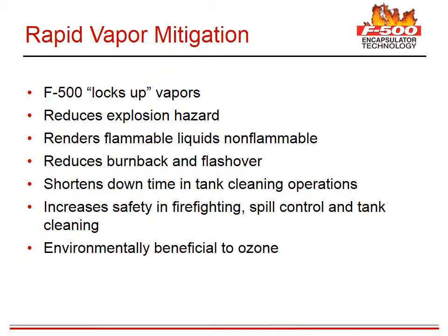In addition to heat and smoke reduction, F500 can mitigate vapors, both airborne and on the surface, by applying a 3% F500 in water application to the source, which reduces explosion hazards, renders the fuel non-flammable, reduces burnback and flashover, and increases safety. These properties also allow F500 to be used for spill mitigation and even tank cleaning. In addition, F500 is friendly to the environment.